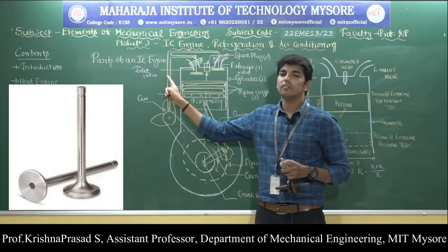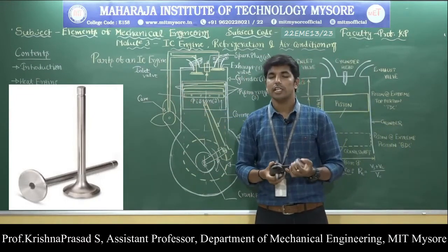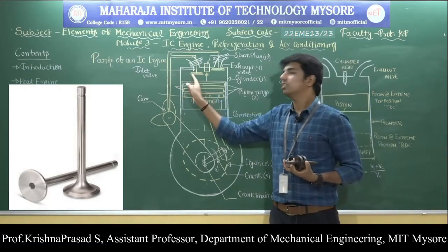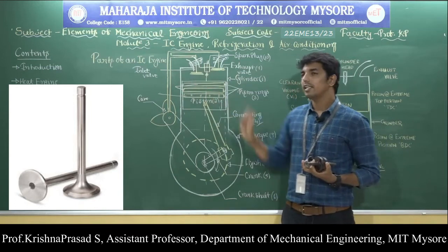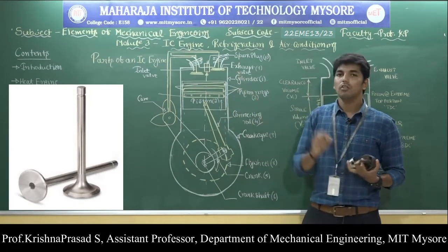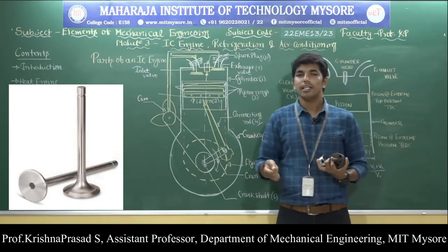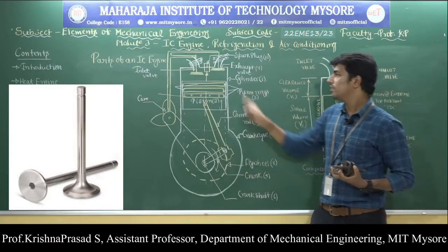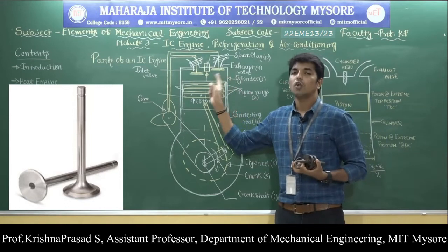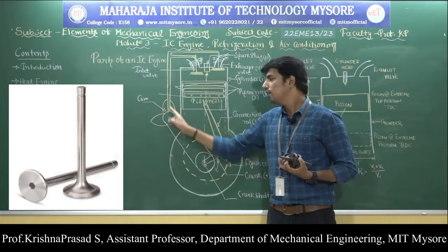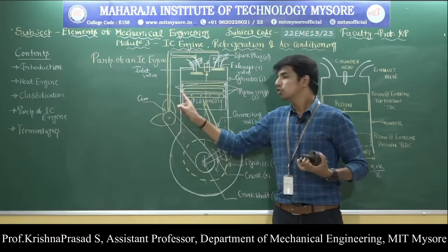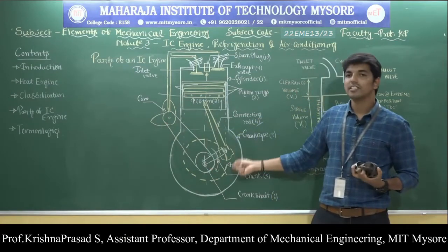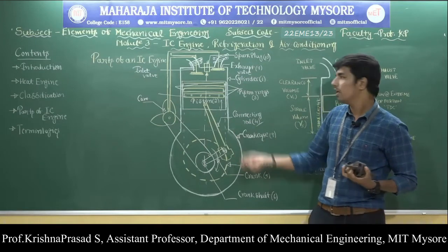What is the main function of the inlet valve? The main function of the inlet valve is to allow the air-fuel mixture to enter the engine cylinder, and the exhaust valve allows the burnt gases to escape from the engine cylinder in the exhaust stroke. These inlet and exhaust valves operate with the help of the camshaft. This camshaft receives power from the crankshaft itself. So this is regarding the valves.